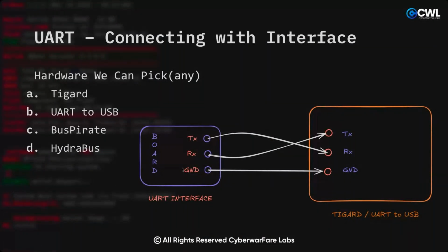So we have to turn on the Wi-Fi router, and TX is for transmission. If we are transmitting data, someone has to receive it. This is why it will go with RX. And from our USB, from our PC, if we are sending any data, it is going to be received in the Wi-Fi board or any embedded device. So ground with ground for completing the connection.